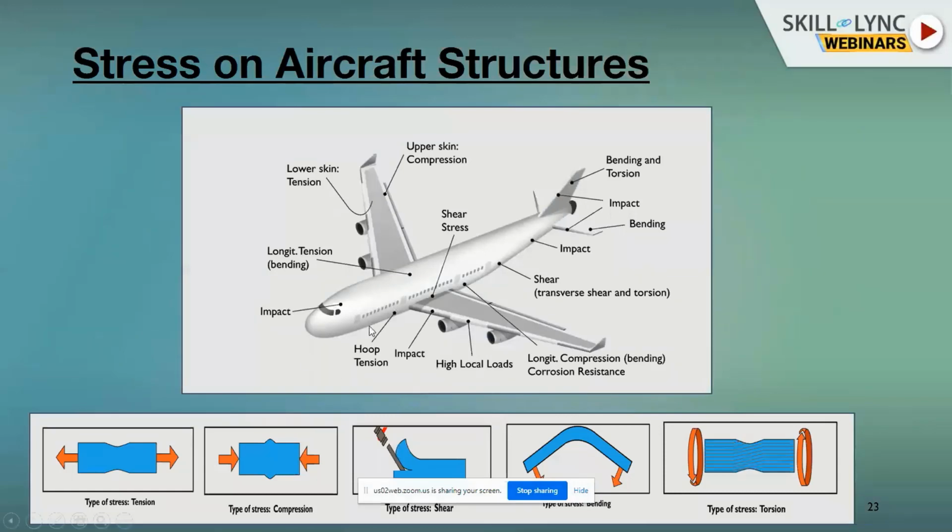So now this is how we basically design the aircraft. The predominant stresses acting on the aircraft, since it acts like a pressure vessel: every pressure vessel is designed for hoop and longitudinal stresses. And always the hoop stress is critical, because sigma is equal to PR by T, whereas the longitudinal is PR by 2T.